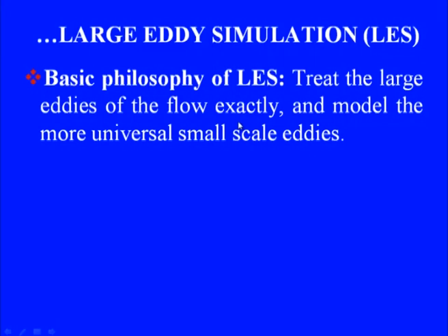So, that forms what we call the basis or basic philosophy of LES, that is to say, treat the large eddies of the flow exactly and model more universal small scale eddies through what we would call a subgrid scale model. And please remember, large eddy simulations are inherently time dependent and 3-dimensional simulations, in contrast to statistically averaged or time averaged Reynolds averaged equations, where we get steady state flow simulations.